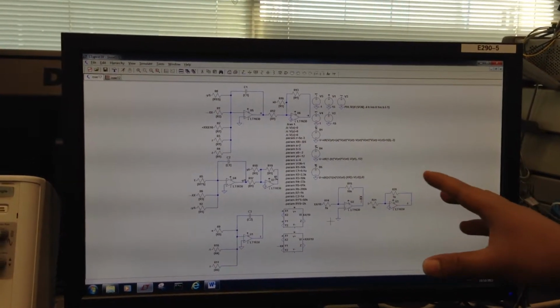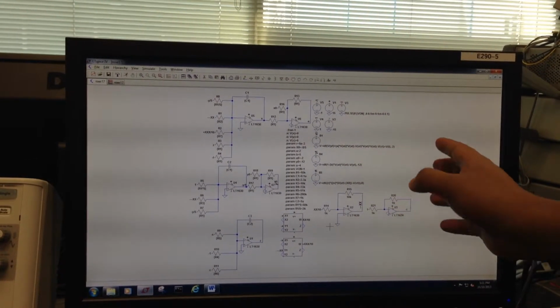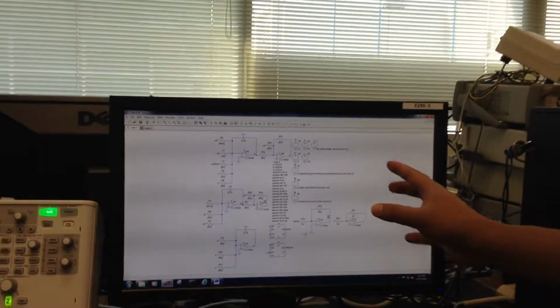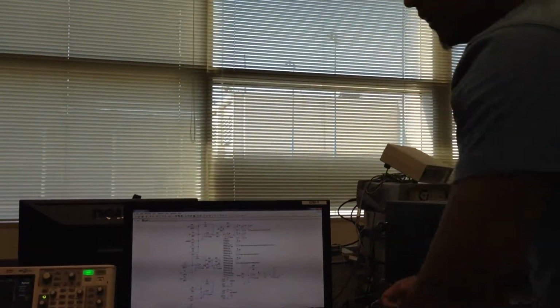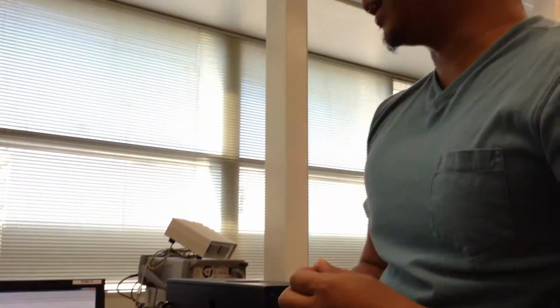For our design we had to scale the resistance, or pretty much the gain, of the op amps so that when you simulate it we don't have to simulate for a long period of time. If we don't scale it, the simulation time is going to take us 16 minutes. So we had to design a circuit to simulate the full differential equation that only simulates within a second.